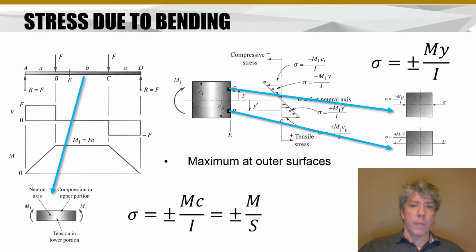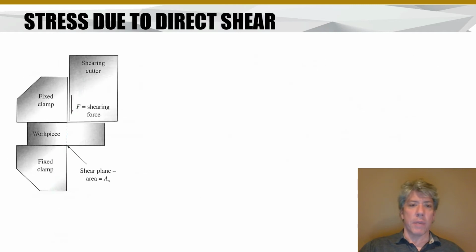So it's really important to begin to remember these stress distributions we've discovered, because you really want to know where the stress is maximum, because that's where problems are going to occur in the material. I guess it would be fair to say you're interested in areas where there's no stress, because essentially those are areas you can usually remove material from and have essentially just as strong a part or beam or whatever the case may be.